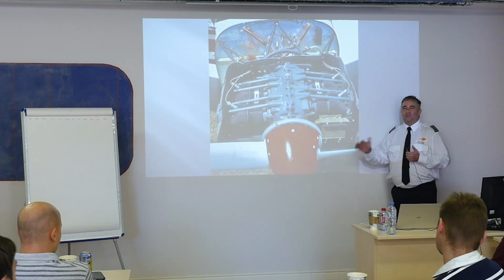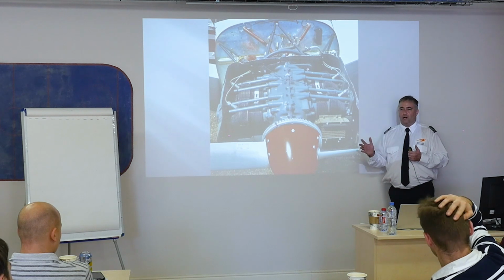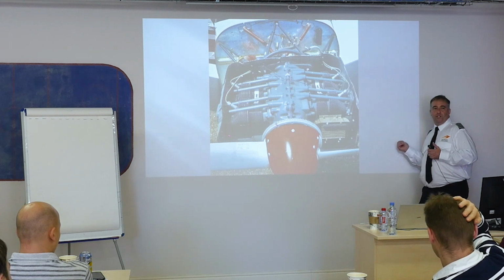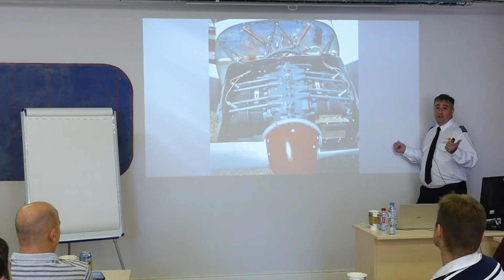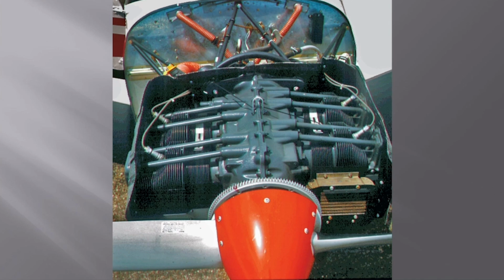If it went any faster than 2,800, 3,000 RPM, you would have serious separation at the tips because it exceeded the local speed of sound. So there is a maximum amount of revolutions per minute that we can have of this propeller. If the engine turns in excess of that RPM, then it has to be reduced through gears. Okay? You won't fly that airplane in the training program. Not for private pilot, not for instrument, not for single engine commercial. All right? And in fact, you may not ever fly one of those engines with gear reduction until you get into turbine airplanes and turboprops, okay?